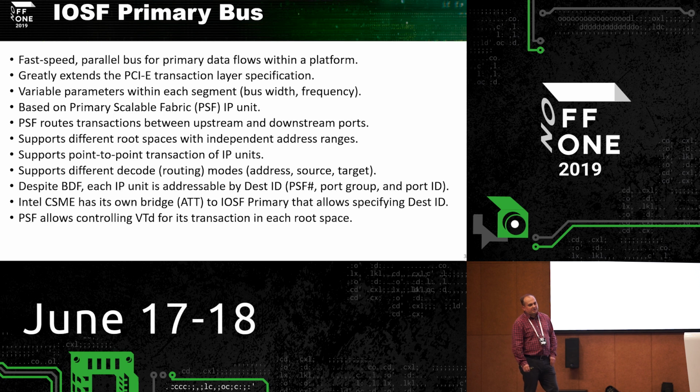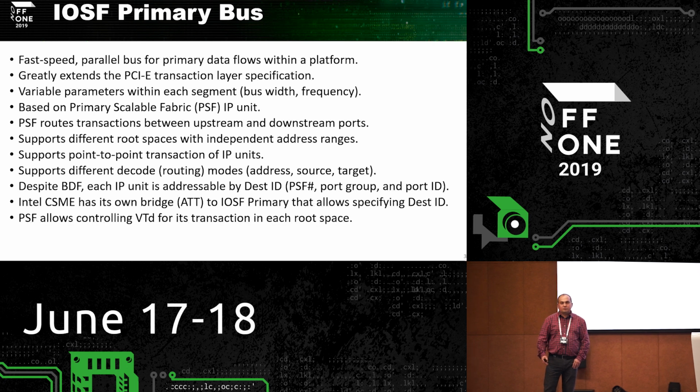It's like the foundation or the backbone of this bus. Actually, it's a router to which different devices are connected through different ports. But the most interesting thing is that in terms of the PCI Express standard, the transaction is routed either based on the address or BDF.